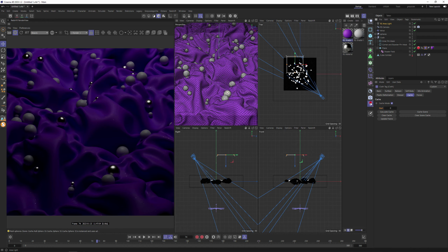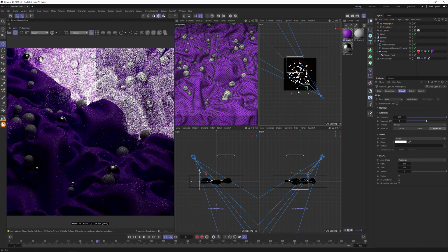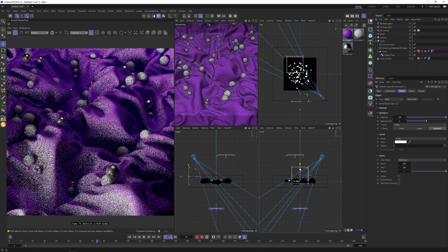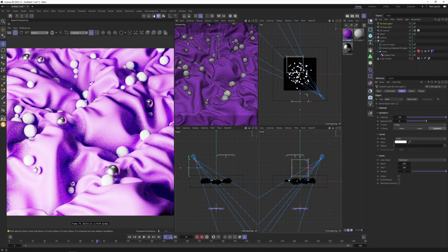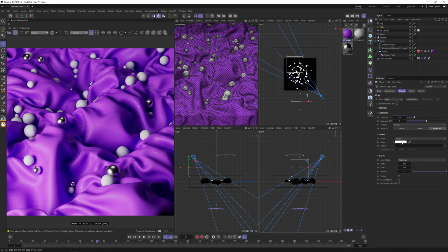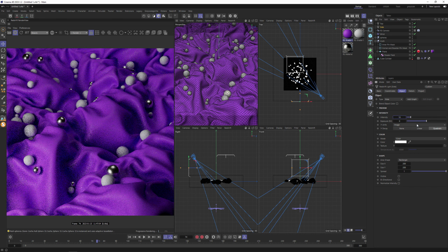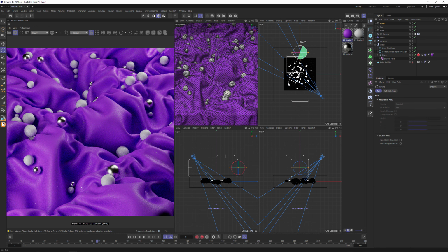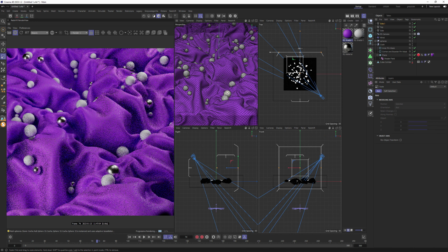Creating one more light and position it to the side, a bit up. We need to rename it, one for top, the other side, lowering the intensity, something like 10. Duplicate by moving while holding control, rotate, upscale it to a huge value.